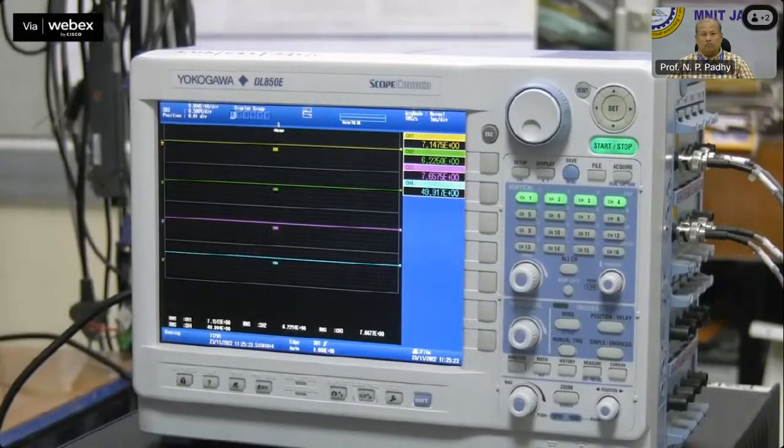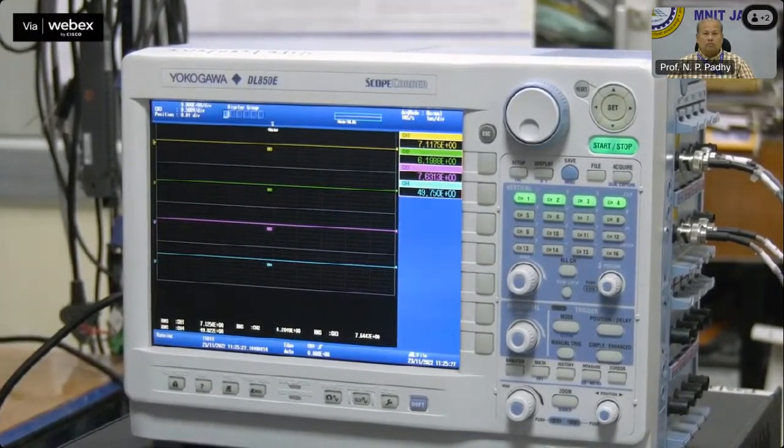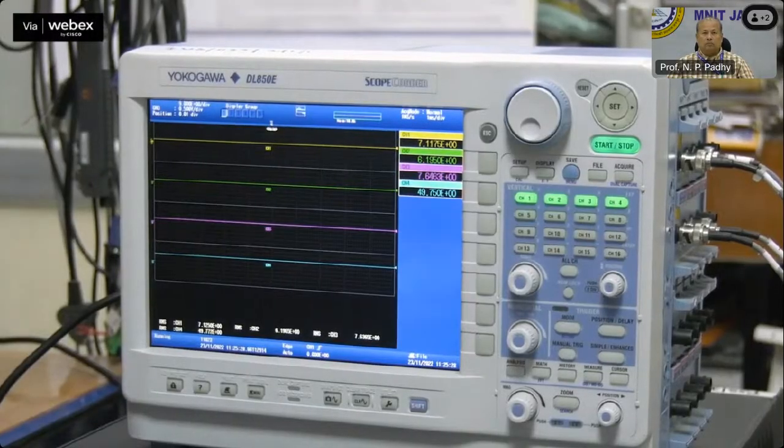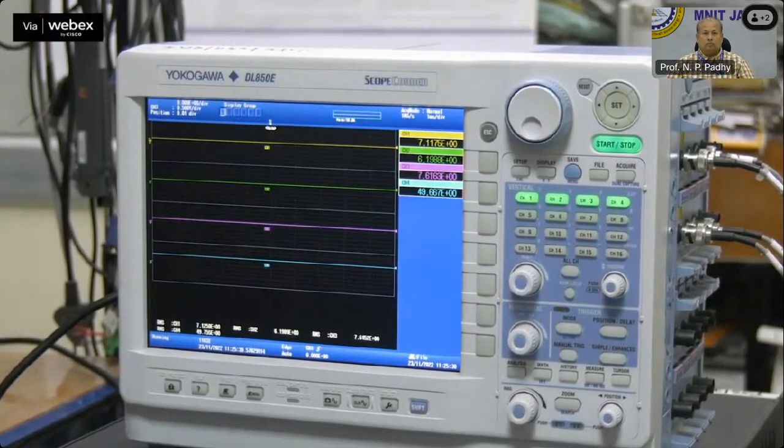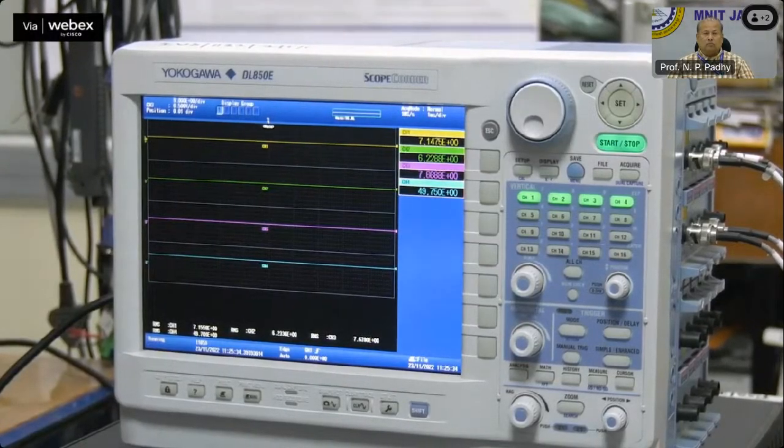The initial DC bus voltage is taken as 270 volt and then it is changed to 300 volt and 260 volt respectively. It can be observed from the DSO that the change in DC bus voltage does not affect the battery voltages or currents, and the DC bus is perfectly regulated.